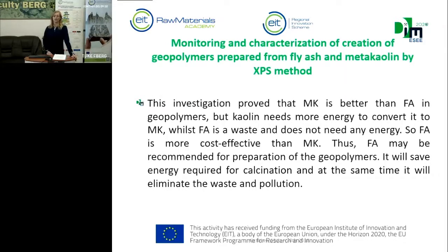This investigation proved that metakaolin is better than fly ash in geopolymers, but kaolin needs more energy to convert it to metakaolin, whilst fly ash is a waste and doesn't need any energy. So fly ash is more cost effective than metakaolin. Thus fly ash may be recommended for the preparation of geopolymers. It will save energy required for calcination, and at the same time it will eliminate waste and pollution.